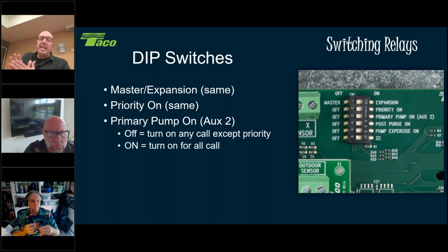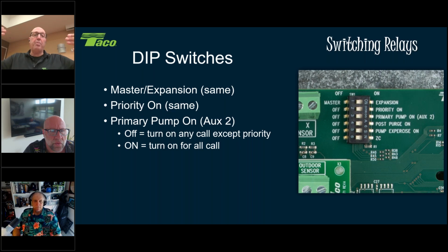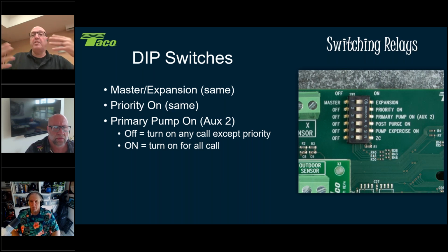the next one here is our primary pump. Now, your primary pump is going to be your boiler pump here. And if it's a boiler that does not have its own internal circulator and you need to control it, it also does depend upon where you put your indirect tank pump. It could be tapped right off of that injection leg coming off the boiler before the pump. That means it depends on how you want that primary pump to turn on, right?